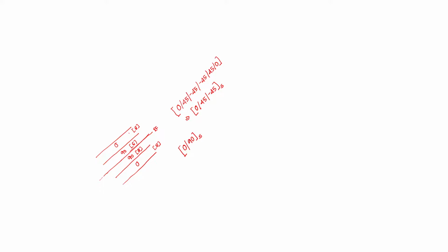What is the significance? This is a simple laminate where, because all the layers are specially orthotropic, there is no shear extension coupling. Okay? So this is cross-ply symmetric laminate. A symmetric laminate could have any fiber orientation.